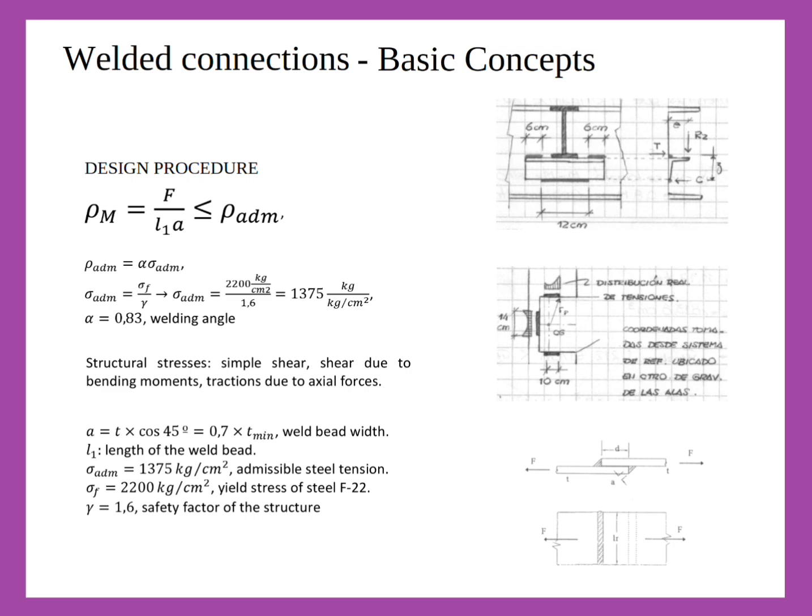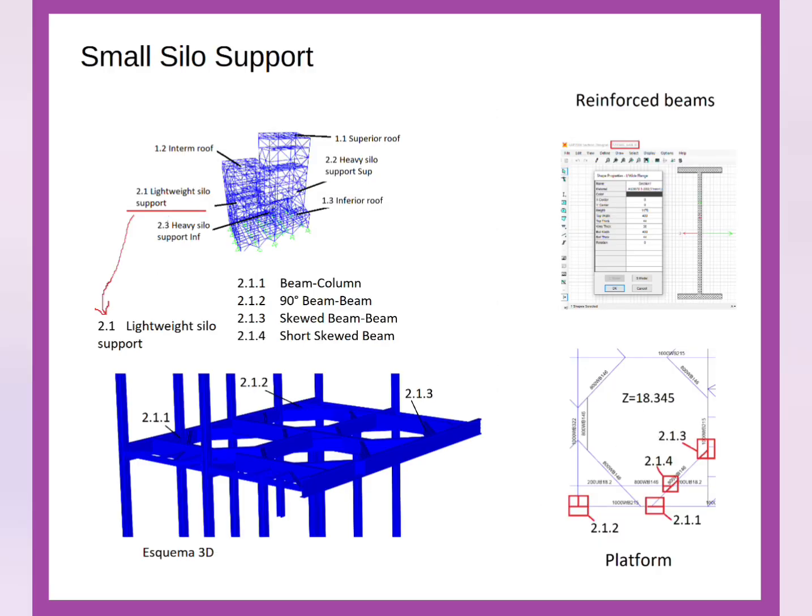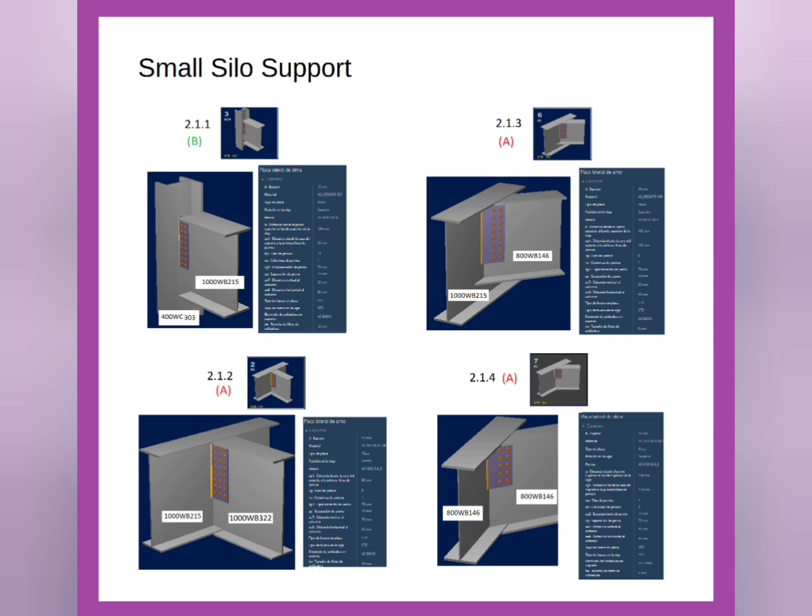Transfer force consists of loads that are transmitted across the joints in the structure. The determination of transfer force can be time-consuming, but it is an essential step in the design of safe and cost-efficient structures. Second, depending on the nature and direction of the transfer force, a series of filters can be used to sort them and obtain the worst-case scenario. Third, once the maximum value has been obtained, the connection elements such as plates, bolts, nuts, etc. must be sized using regulatory values. At the end, the stress values are entered into RAM Connection, taking care not to make mistakes and carefully checking the input data format.